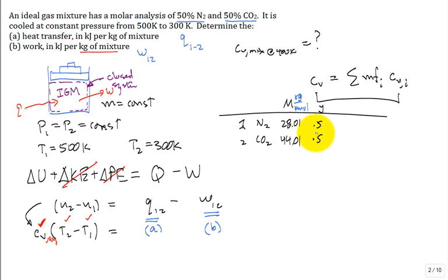So we then put our given mole fractions, 0.5, 0.5. We assume 1 kilomole to start the whole analysis with. If you have 1 kilomole, guess how many kilomoles you have of each of them? I know it's kind of a silly little step, but I find it helpful to say I'm going to assume I have 1 kilomole of the total mixture. How many kilomoles of nitrogen would I have? 0.5. Then I say, if I have 0.5 kilomoles of nitrogen, what is the mass in kilograms that I have? It's just the product of 0.5 times 28.